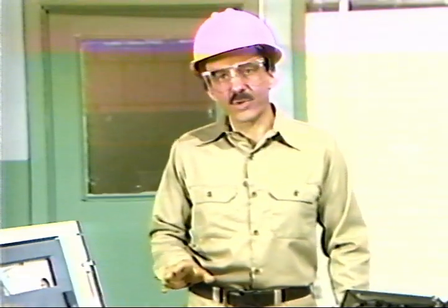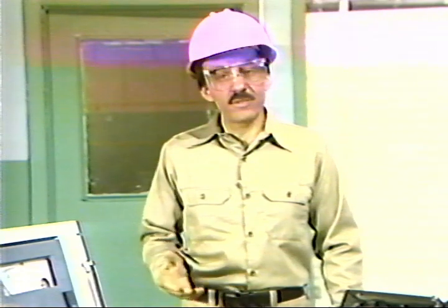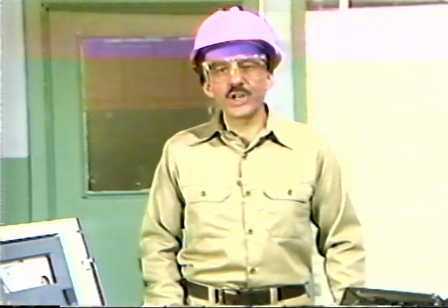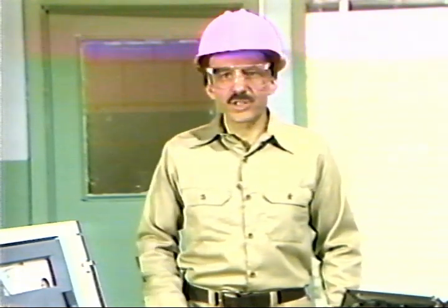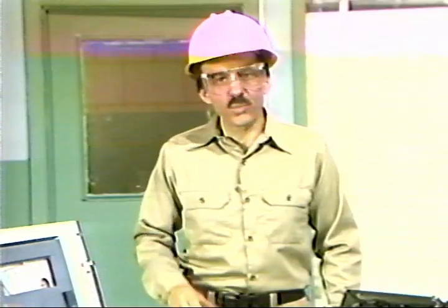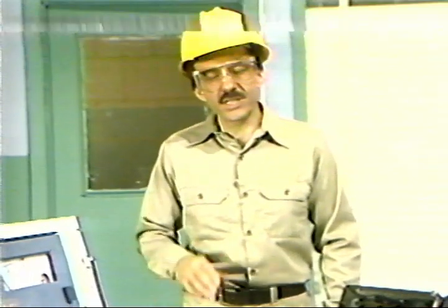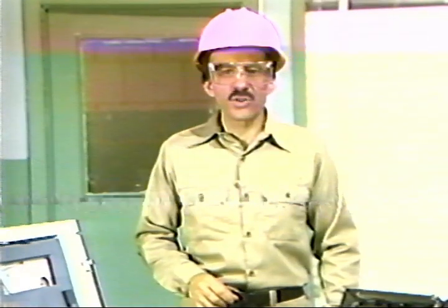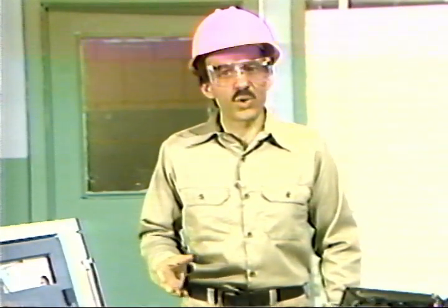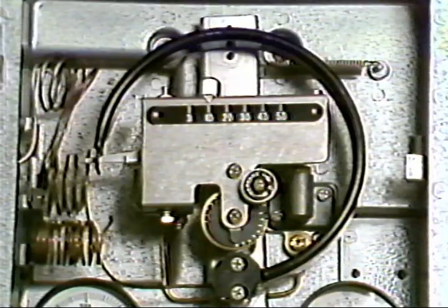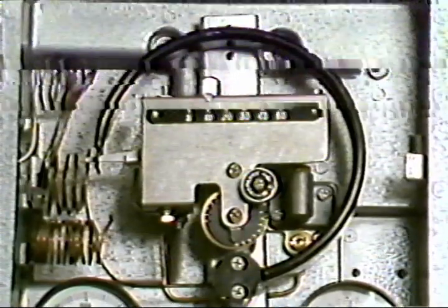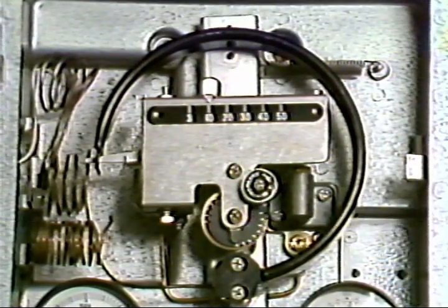The corrective response that a controller provides can take many forms. As you probably know, pneumatic control systems control process variables in different ways. The output response that a controller provides because of a process disturbance is called its control action, or control mode. Most pneumatic controllers can be divided into groups based on the output response they produce when a process variable deviates from set point.